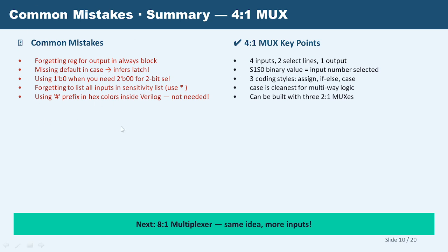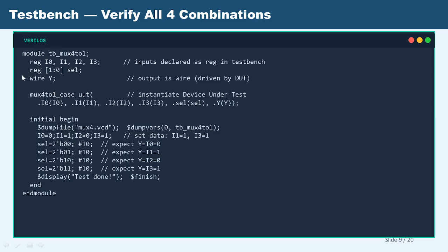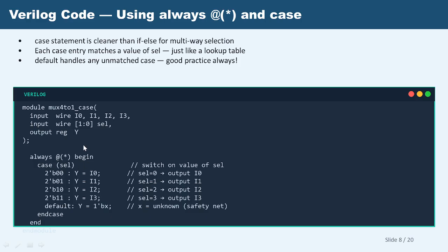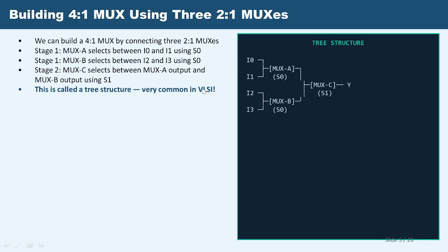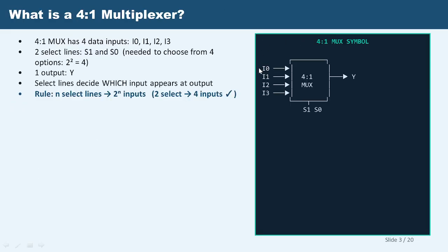I did mention something called reg, right? I forgot to explain it. See why we are mentioning reg in the design code. Just look. Now you have a multiplexer. This is the design of your 4 to 1 multiplexer. Here you are passing inputs. For inputs, you have wire, right? Why do you need wire? Because this input is coming from some other components.